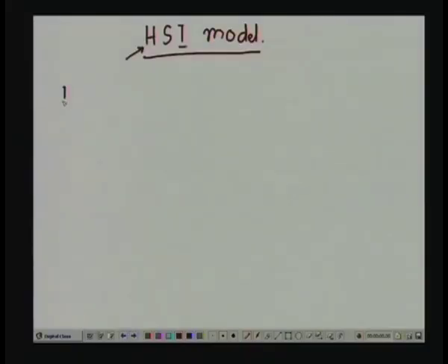Similarly, saturation indicates how much a pure spectrum color is diluted by mixing white color into it. If you mix white into a pure spectrum color in different amounts, what we get are different shades of that spectrum color. And I, the intensity, is actually the chromatic notion of the brightness of a black and white image.